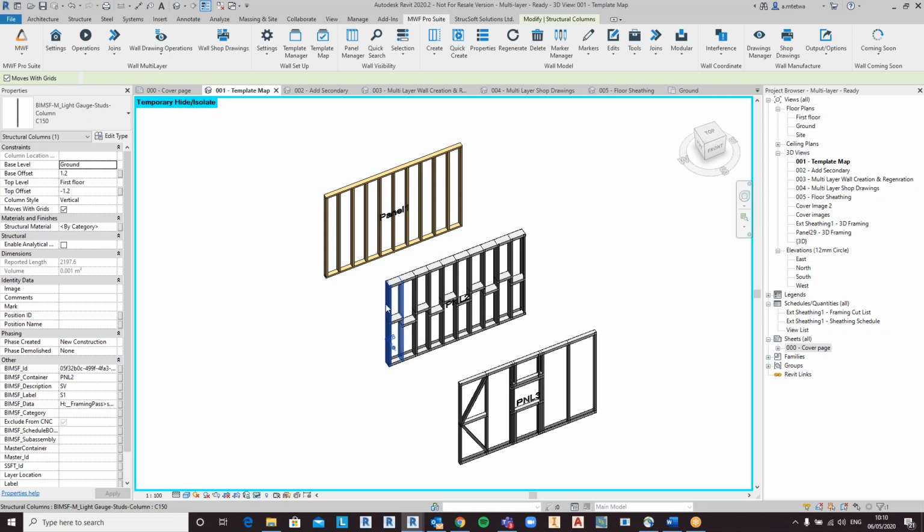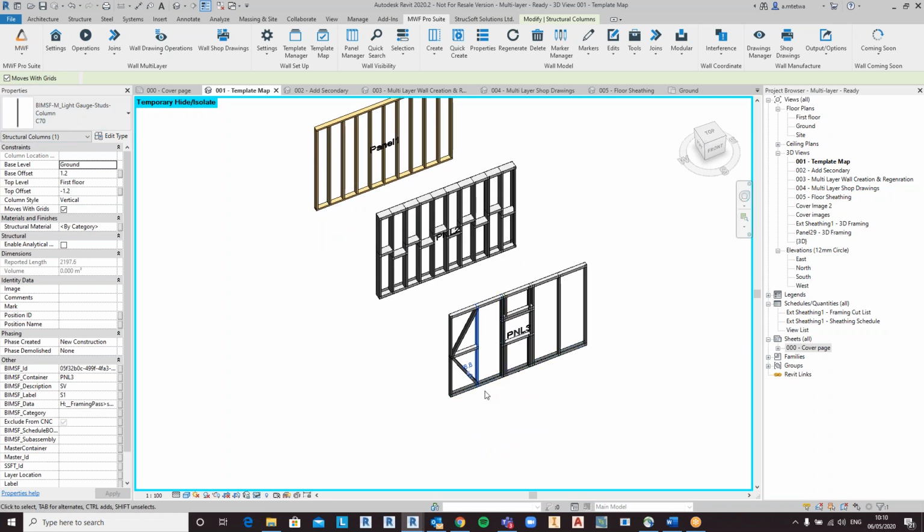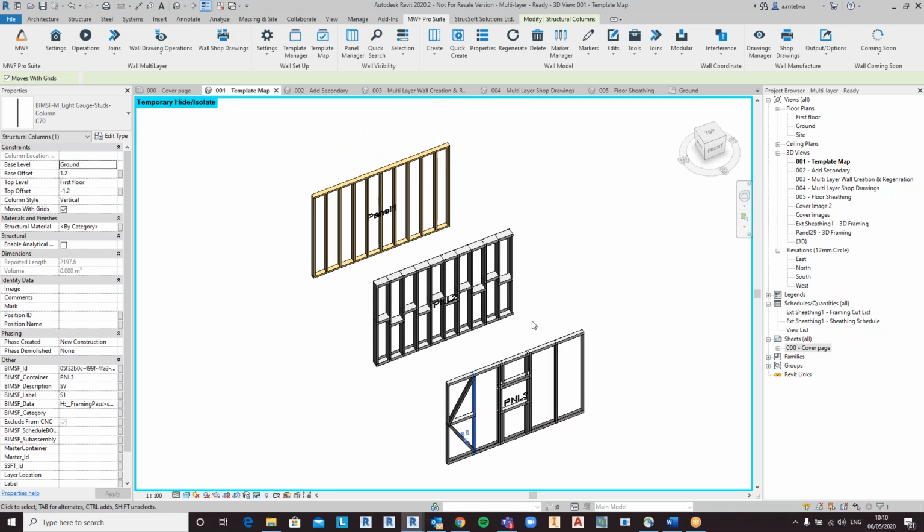However, I have a horizontal stagger from end 1 to end 2 of the panel. And I have finally over here my 70 mil studs with 600 spacing, as well as consideration to the opening. So for instance, I went on the properties and chose to have 2 headers over the top of this and leave it at 1 sill at the bottom. And I've also applied a K-bracing at the side of the panel. So these are just some very simple alterations and modifications you can make to your panels within the properties. And these are easily saved within your template manager and can be applied on other walls.